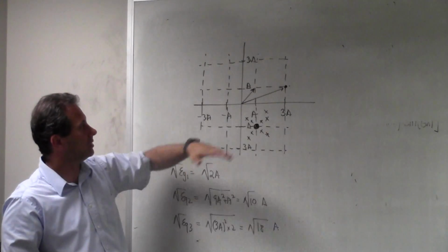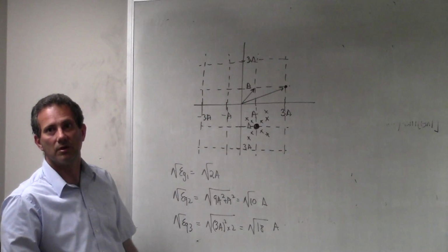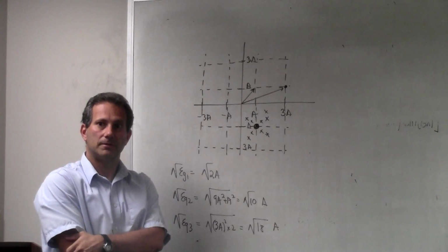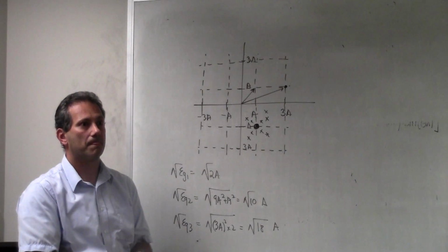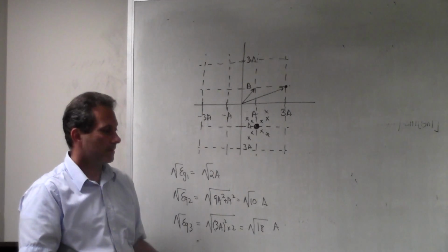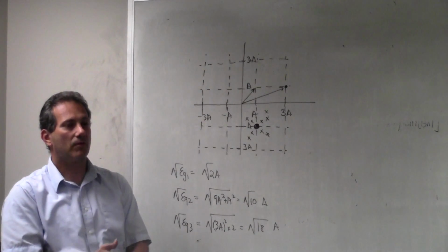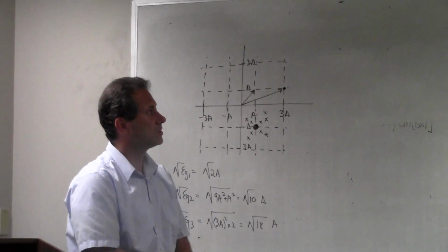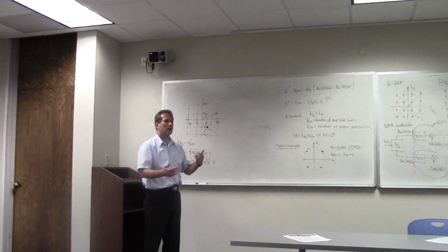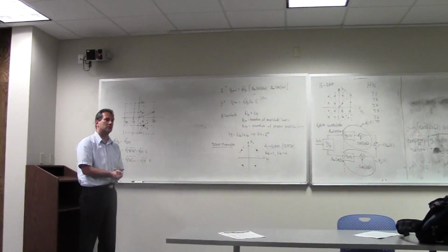And then that results in a particular constellation here. We'll come to that when we start calculating in detail. But now our signals don't all have the same energy, and that is bad for our power amp? Yeah, exactly. It's bad for our power amp, but it's more efficient in terms of how much information you're transferring for an average power.